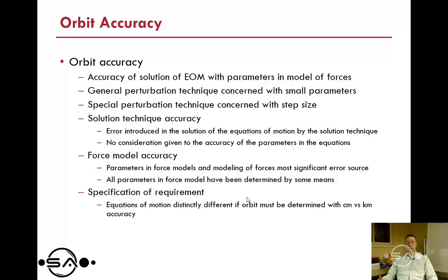Typically, you'll see eccentricity concerned because that will drive some of those small parameters in the force modeling, or special perturbation techniques where we take some initial condition that we've provided and we're solely concerned with the step size. Now, for those special perturbation techniques where we're focused on the solution technique accuracy, really our error is introduced in the equations of motion by the technique itself, and so our focus is on that numerical integration process and the step size in order to drive the accuracy.